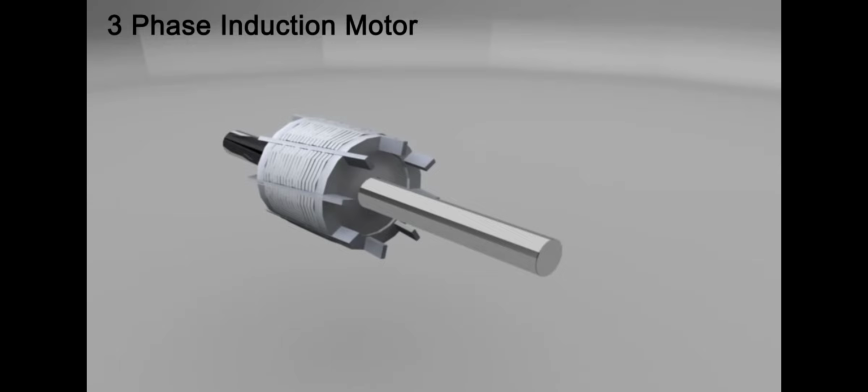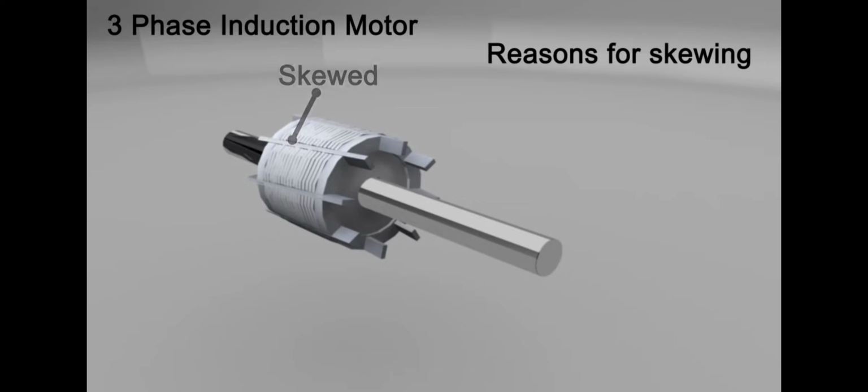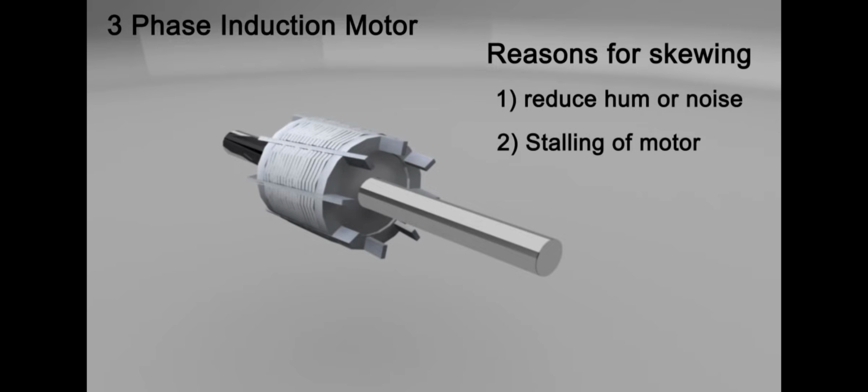The slots are not exactly made parallel to the axis of the shaft but are slotted a little skewed for the following reasons. Number 1. They reduce magnetic hum or noise. Number 2. They avoid stalling of the motor.